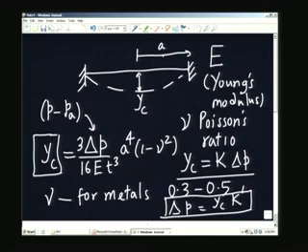So, if the radius of the gauge is known, the thickness of the material is known, and the material's properties, the Young's modulus and the Poisson's ratio, are known, then we directly have a formula which gives the value of k prime. Or I can use a calibration procedure, like what we discussed with respect to the Bourdon gauge, to calibrate the instrument. Instead of looking at all these properties, which are subject to their own errors, and we do not know exactly what these values are, we can actually calibrate the instrument instead of going through a formula like this. But the formula helps us identify the fact that there is a direct linear relationship between the displacement and the pressure.